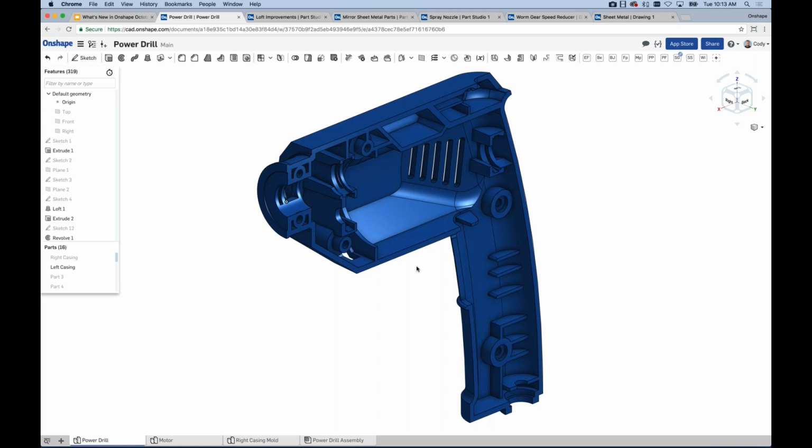And this is really important when we talk about mold making and the ability to create moldable designs that can easily eject from the mold. Draft is a very important value for that. And you want to have generally a draft of a certain angle or more depending on a number of different factors. And so the ability to check all the faces and say, do these faces have enough draft, is an important step in the process if you're doing that. And that's where draft analysis comes in.